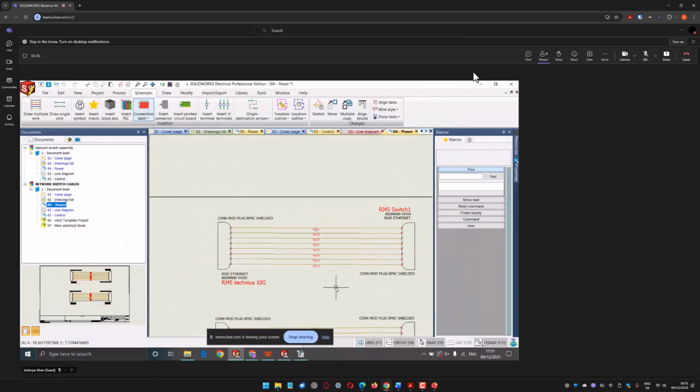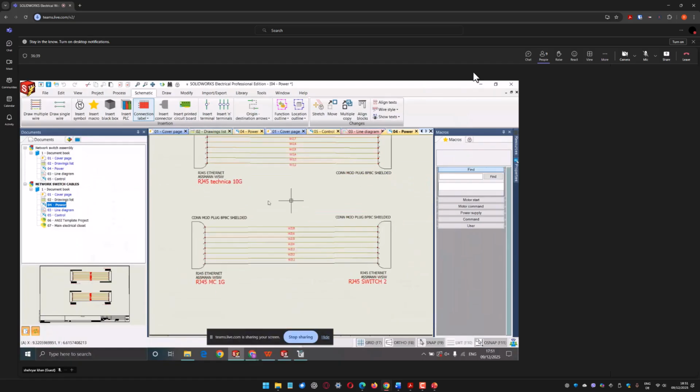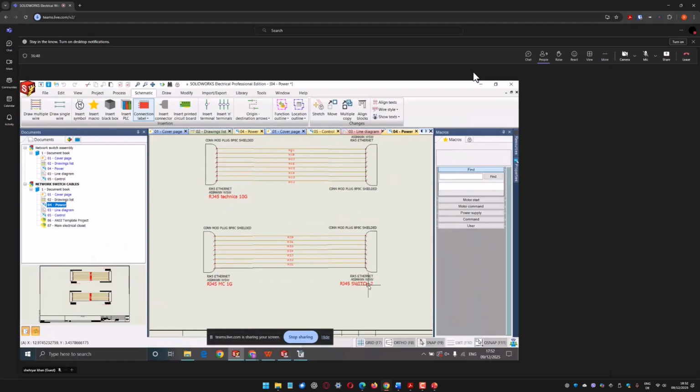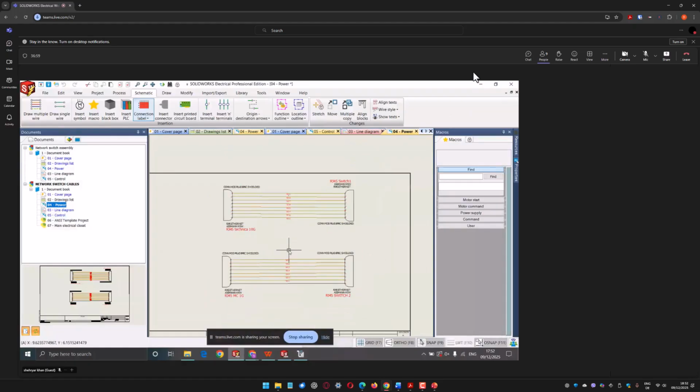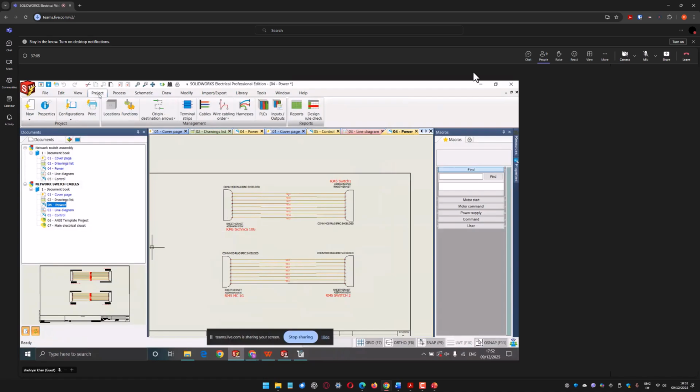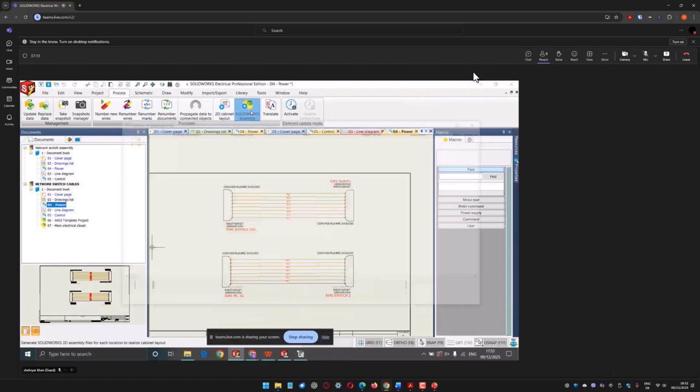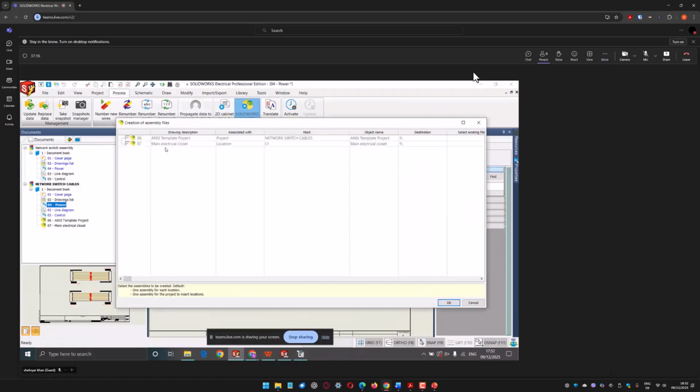And then again, similarly, I'll create another connector here, which means that it will be the same as that, but with different properties, because it's going from RJ45 switch 2 to the 1 gig connector, and here it was, I think, 10 gig connector. Yeah. And once everything is done here in the schematics, you can go to your project or also your process, and then you'll start populating your SolidWorks assembly, which you link with your template project. It will create assembly and link it to the template project.